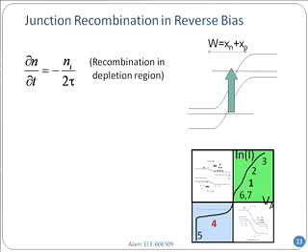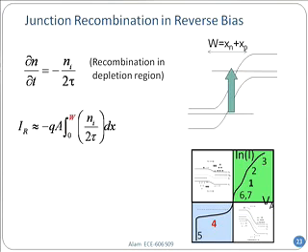Now that was all about the forward bias side. That's fine. On the reverse bias side, the answer is very simple, fortunately, because in the reverse bias side, again, you have done it in homework. Have you? In the reverse bias side, you do not have any carriers. N and P are both 0. And so therefore, the generation current is Ni divided by tau. You have done this in the last homework. So you can integrate it out.